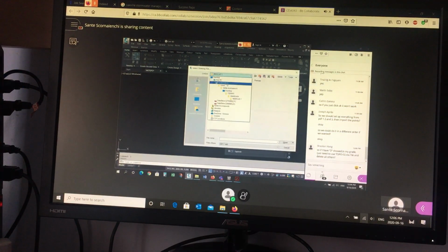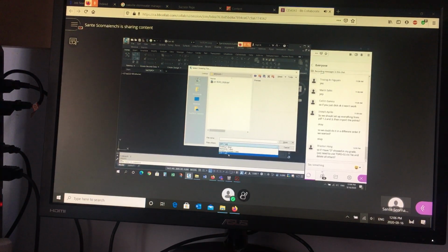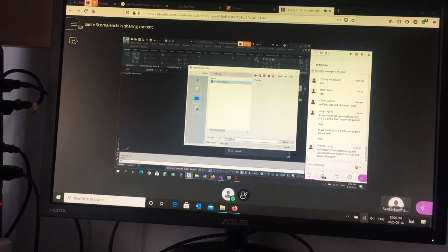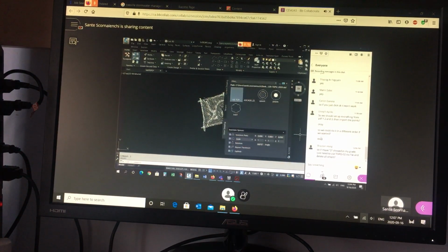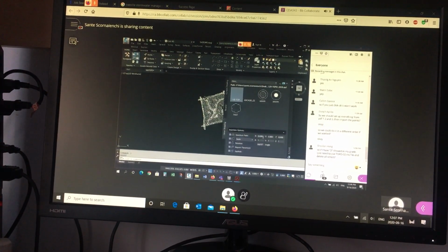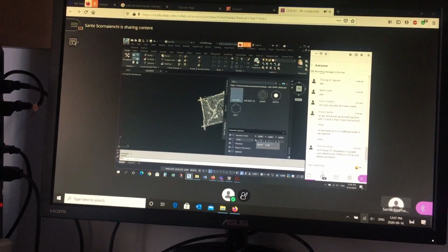Navigate again to your desktop under course code, under downloads, under module 1. If you don't see it, change the file type to DXF. Choose the file. That's the same for everybody. The plan layout is the same. The elevations are different. Okay? So everybody uses the same file. Say open. And before you bring it in, make sure all of these are off. So you use the defaults. Bring it in at XYZ 000. Scale 1 for all 3 axes and rotation 0. Okay, so make sure everything here is off. There it is. If you double click on it, it'll bring it into the drawing. So double click.